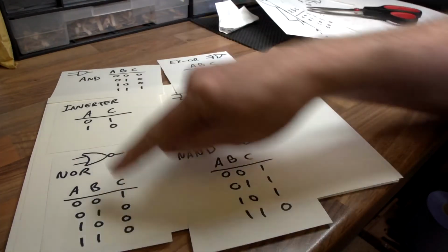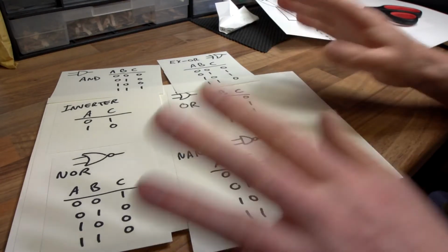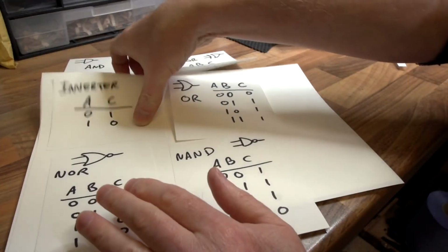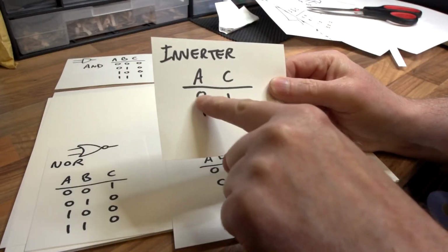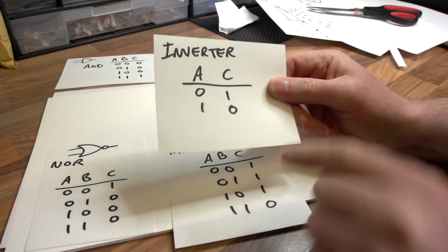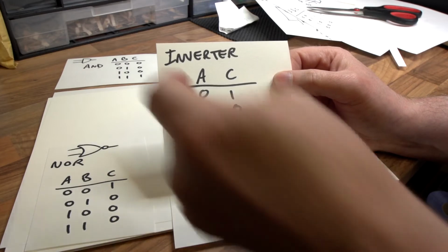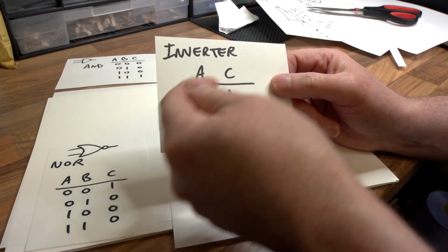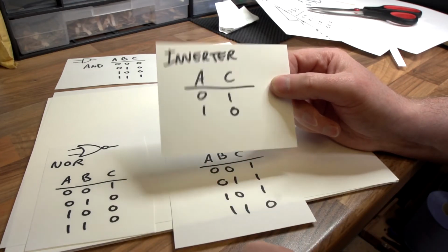If you know these truth tables for these gates, then you pretty much can do anything to do with logic. These are the building blocks that everything else is based on. The only other gate that I haven't talked about is what I call a buffer, which is not an inverter, it's just a straight through. So a 0 would equal 0 and a 1 would equal 1. It's not really a logic function because it doesn't transform the input to the output. It just simply passes straight through, and all it does is current amplification. So you can have a small signal coming in and a big signal coming out. It's called a buffer amplifier, if you like, or a buffer gate.